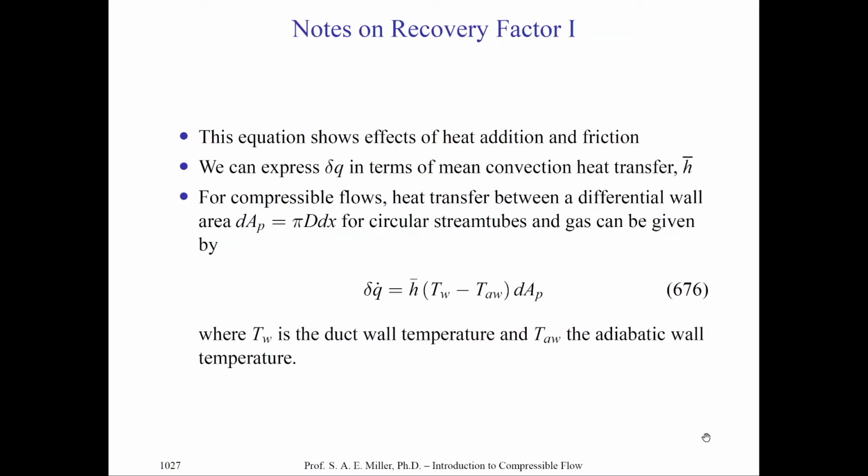Now, analyzing this equation, we can introduce, finally, the recovery factor for these types of flows, which will be introduced again later in the class when we talk about high-speed boundary layers and hypersonics. We see that this equation shows how heat addition and frictional effects are indeed related. And we can try and express the heat transfer change in terms of a mean convection heat transfer, H bar.